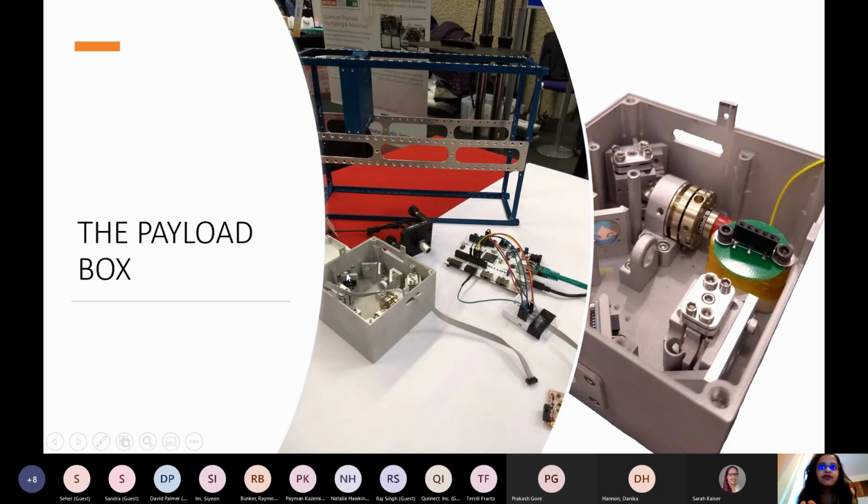If people can see this tiny little hole where my pointer is, outside of that hole will be the telescope, and this little mirror just behind the hole we can steer using voltages, so that we can align the light to go out of the hole and directly into the telescope as we want, so that the telescope can then send that light out into free space. And we can also steer the mirror as well as the satellite together to ensure that the light reaches the ground station.